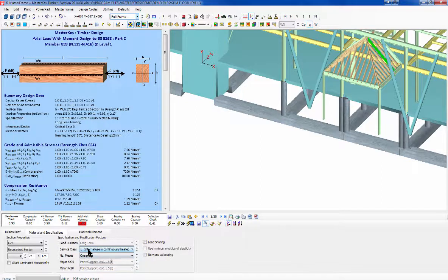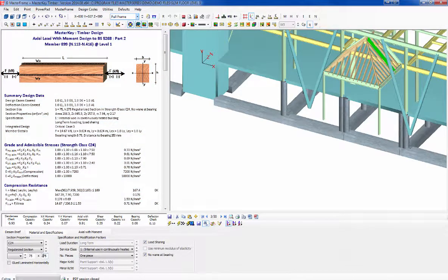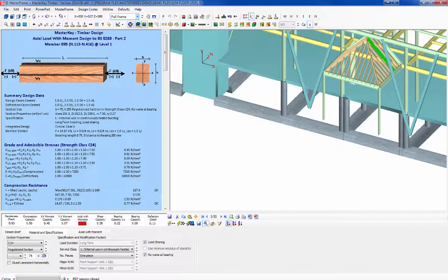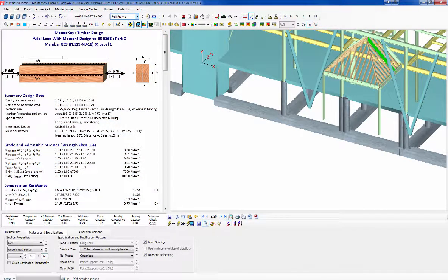It is internal, continuously used, and it is one piece, but it does have load sharing, which helps us a wee bit. But everything else, we would need to make that a bigger section. So if I went 275, a bit extreme, 250, 260 would work if you got that section size. But again, it's very straightforward, and all we're demonstrating here is our ability to do timber inside the frames. I wouldn't necessarily dream of doing it in this sort of model, but if it was to be timber, that's not a problem.